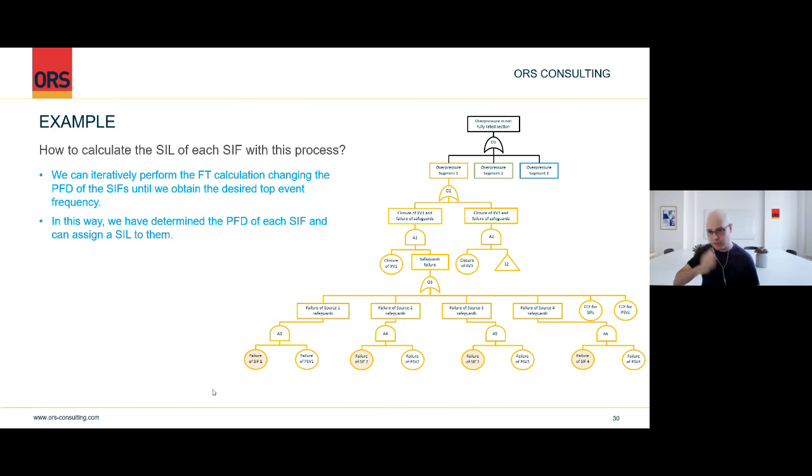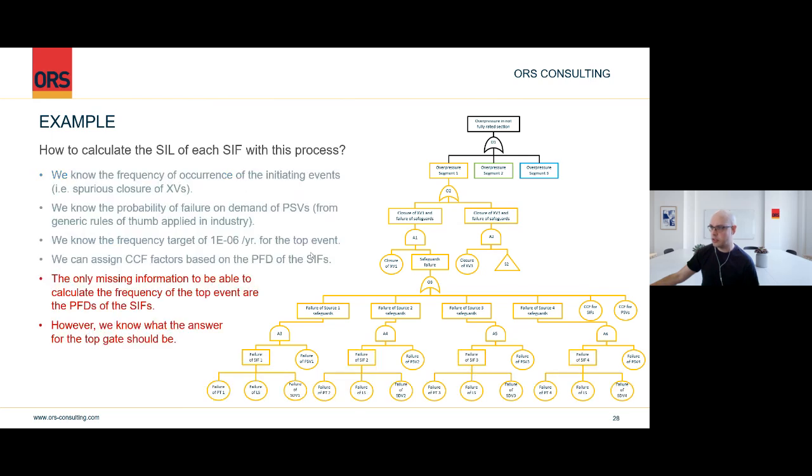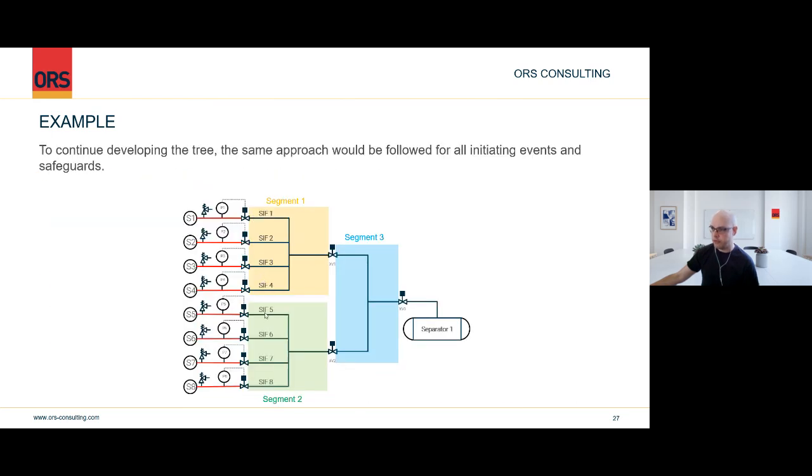I would even stagger the proof test to make sure that I'm decreasing the probabilities of common causes failing, right? So maybe you have different maintenance crews doing them every 6 months. Every 6 months you do 1, 3, 5, and 7, and then the next 6 months you do 2, 4, 6, and 8, by 2 different maintenance crews or something, to make sure that we are doing them independently.